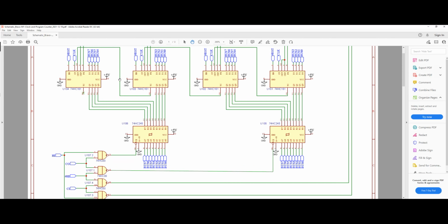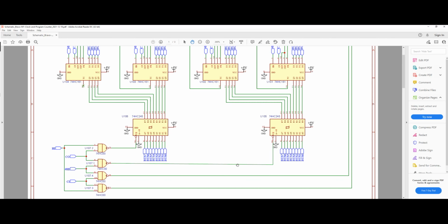So let's say that we have a value in our program counter, and it's a 16-bit value, and we want to put that on our bus. Now, if you look at these transceivers here, they have, as I mentioned, pin 19, which we normally connect only the counter out signal to, right? This is an active low signal.